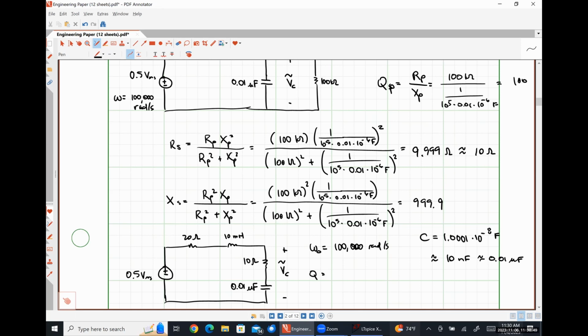Our Q factor, though, is going to change pretty significantly, right? So now the R that goes into our expression for our Q factor, we just had omega naught L over R. Earlier we had 50. Now we have 33.333 repeating.